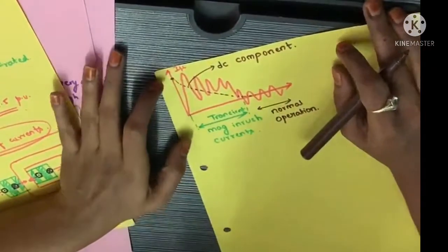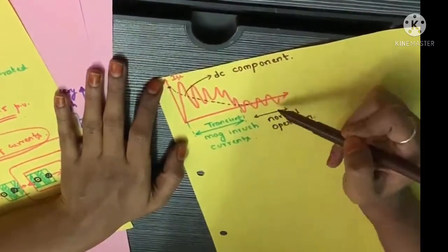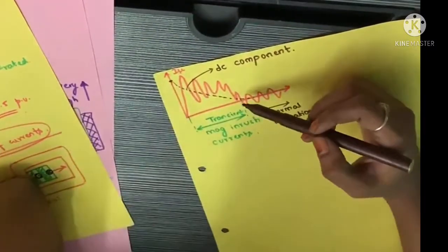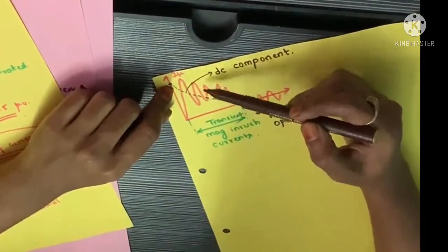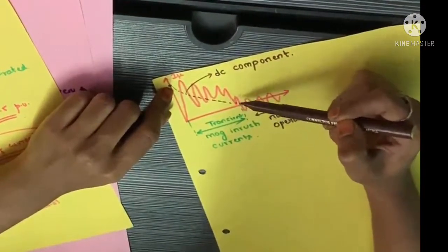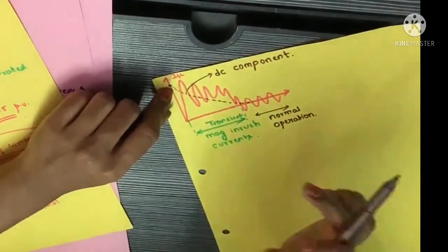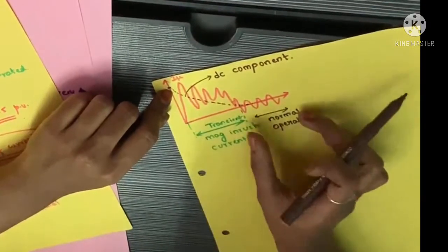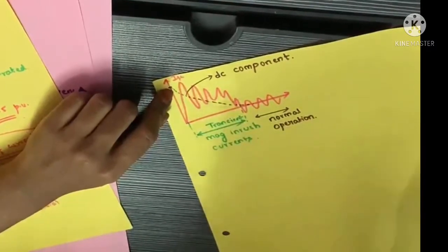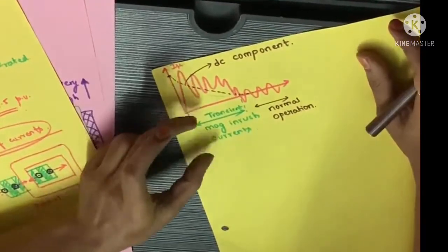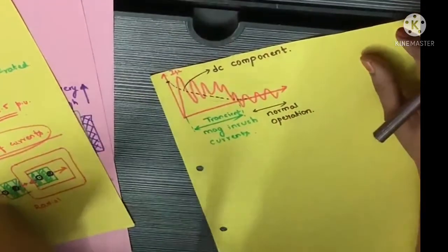As we can see, this is the representation of magnetic inrush currents, that is, the I mu waveform. When a transient occurs, the I mu attains a very high value, and it starts decreasing as the transient period comes to an end, and then it reaches its normal waveform. This part we call the transient period, and this is the normal period. As you can see, this is the DC component of this I mu. Initially the negative wave of the I mu is absent, because the flux during one cycle is unidirectional.